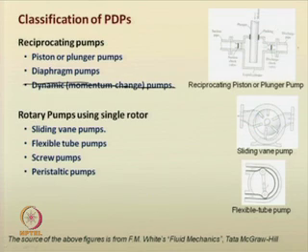We have quoted this figure from the Tata McGraw-Hill published book Fluid Mechanics. From the figures we can see the sectional views of the reciprocating pump. It consists of liquid chambers, suction check valves, and the inlet. So, the cavity portion is there, then it opens, then it rotates, then it gives the discharge at this location.